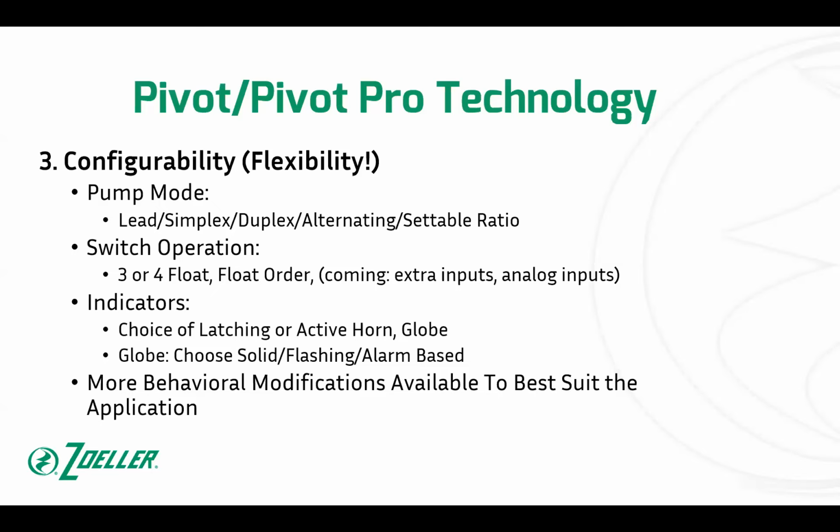Even our panels, you're going from duplex to simplex, you got to rewire the float switches so that the panel doesn't go into alarm every time it tries to run that down pump. Duplex and alternating, they're both alternating. What duplex will do is allow both pumps to run simultaneously if there's a lag float that comes up. In alternating mode, even if a lag float comes up, it will only ever run one pump at a time.